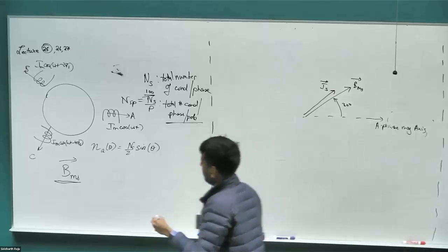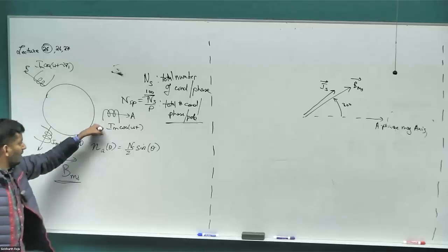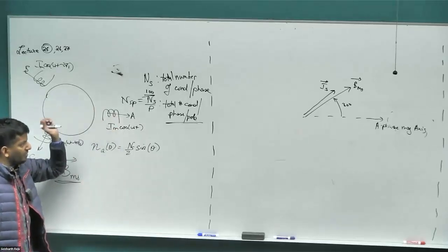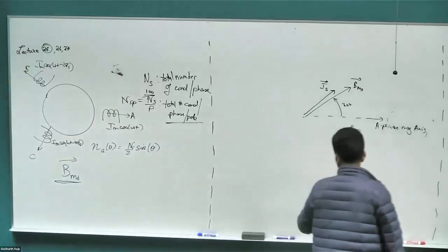Right, because again, going back here, if I were to look at what the stator current space vector will be at time t equal to 0, the A phase current would have been at its maximum. And what is the idea of a space vector? Again, it's tracking where the maxima is. That's all it's doing. There are other ways of looking at the same thing as well.